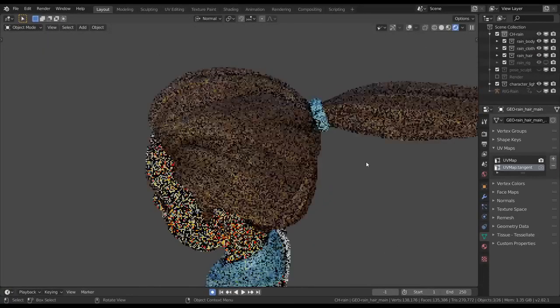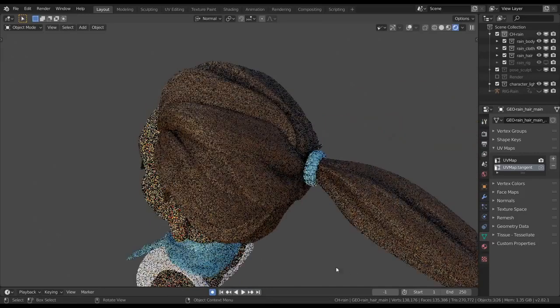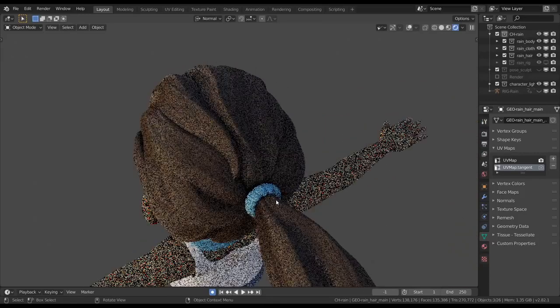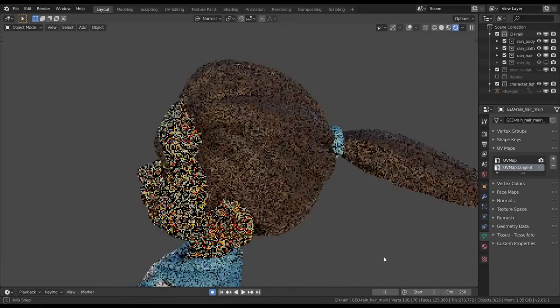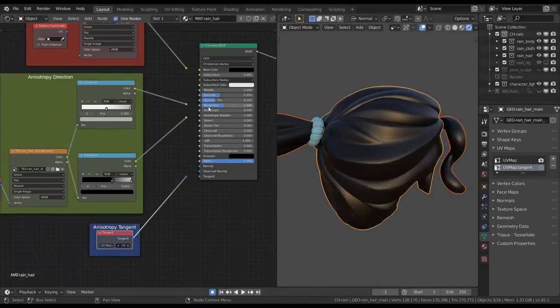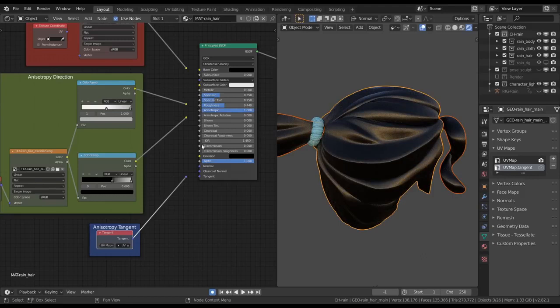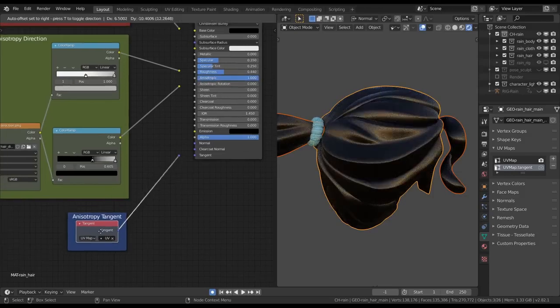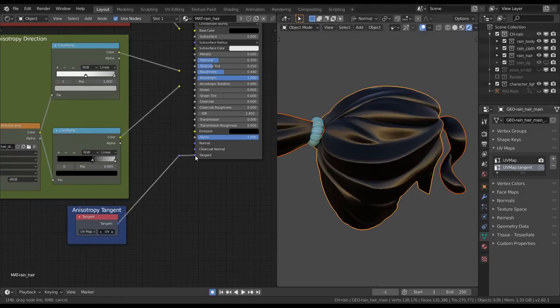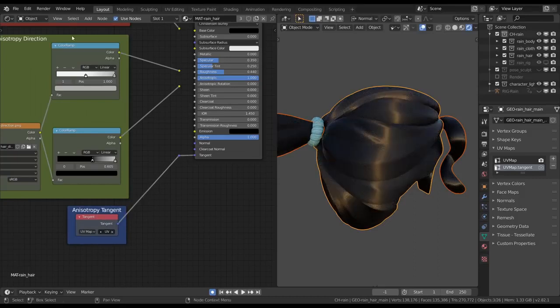To give a nice fake hair look on modeled hair, I can recommend the anisotropy shading, which adds a directional distortion to the glossy highlights. Turning the anisotropy to 1 by itself is not really going to look convincing or even good, since it just adds a spherical pattern based on a world axis. You need to create a second UV map, add it as a tangent node, and plug it into the tangent input of the shader.